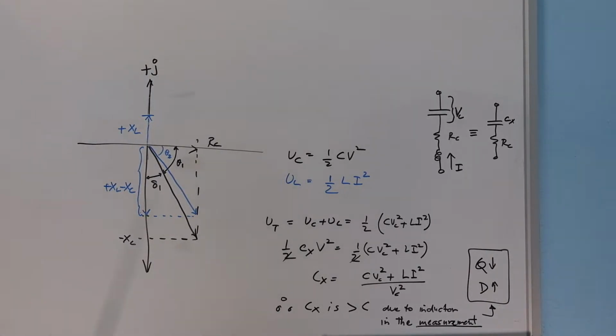So purely from a measurement point of view, I've done some measurements on capacitors with inductance added to them in series, and that basically has resulted in a measurement that is indicating a higher capacitance. So I'm thinking this is a measurement effect, possibly not a real effect, because what is going on is that when a measurement is taken by an instrument, it's trying to read the capacitance of that particular device, and is somehow measuring the energy in that particular thing. Effectively, it comes down to measuring the energy and then converting that into a capacitance value.